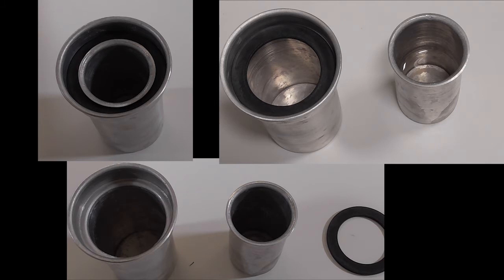Our heating system consists of a calorimeter, which has 3 components to it: an inner cup, an outer cup, and a spacer. The spacer allows for our system to become insulated from the outside, or as insulated as we can get it. The inner cup we fill with water, specifically distilled water, up to about 50 milliliters of water or 50 grams, so that it completely covers our heating element.